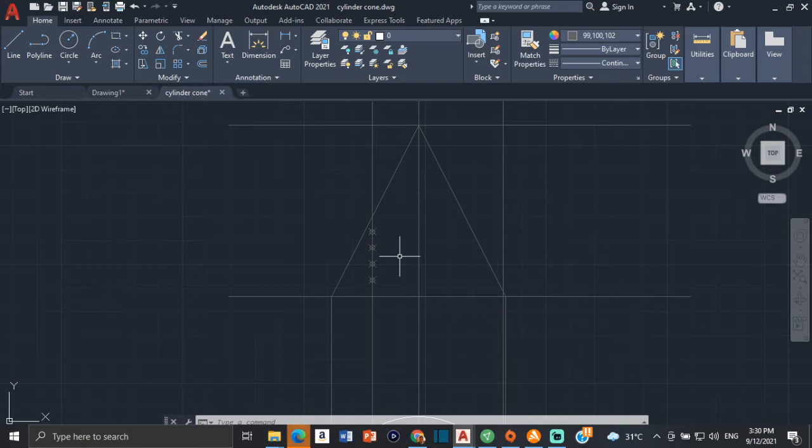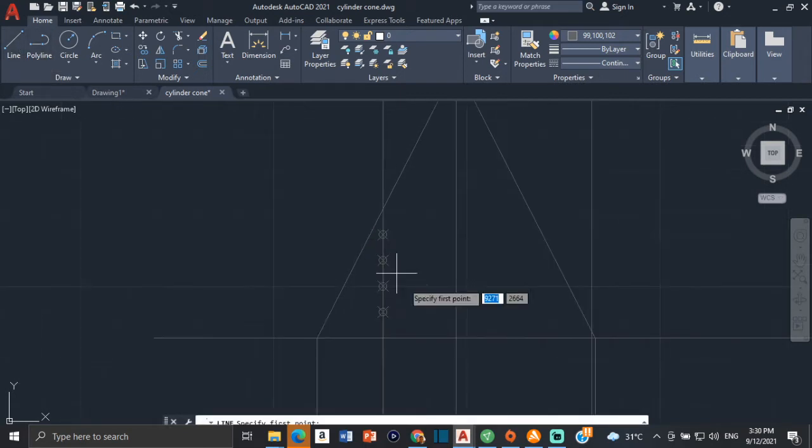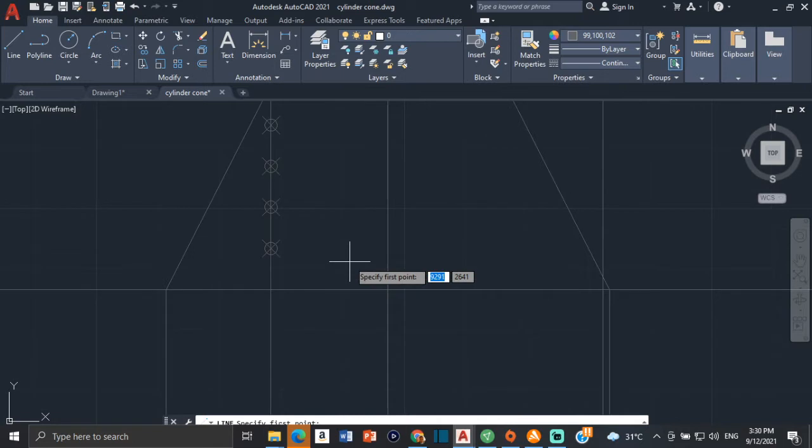So you're just going to divide that line from the base here to where the cylinder meets the cone. Divide that into a number of segments. In this case, I chose 5 equal segments. It doesn't have to be 5 and it doesn't have to be equal. So then what we're going to do is this. We're going to draw some horizontal lines.